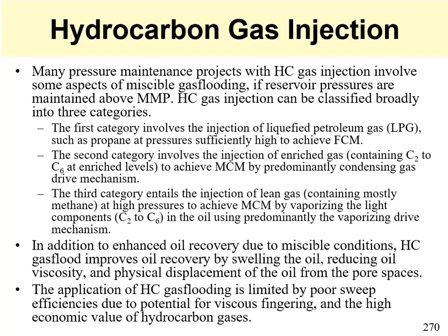So in addition to the enhanced oil recovery due to miscible conditions, injecting hydrocarbon gases improves oil recovery by swelling the oil, reducing oil viscosity, and physical displacement of the oil vapors. However, there's a downside to it.